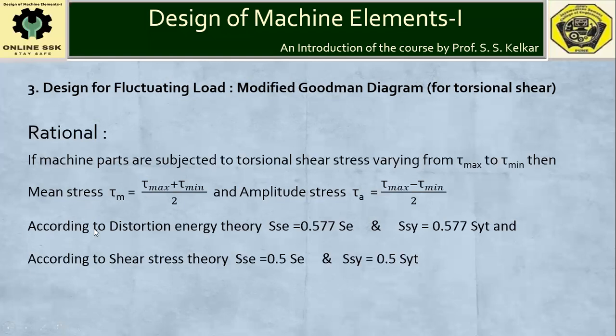So in the problem statement, they will provide the information regarding which theory is to be implemented. If not specified, you can employ shear stress theory, and based upon which you can calculate SSE as 0.5 times SE and SSY as 0.5 times SYT.